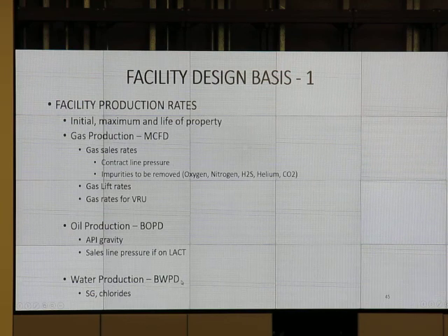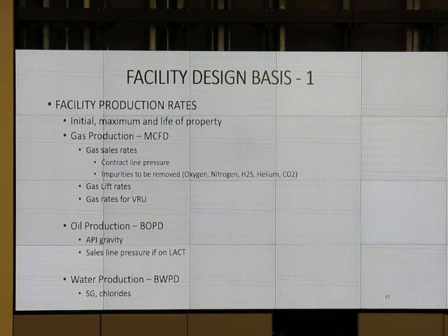Water production. How many barrels of water per day am I going to be handling? What's the specific gravity? The chloride content. I need to know all those things. They're important for corrosion protection. What's my metallurgy have to be? What other materials can I consider for that?